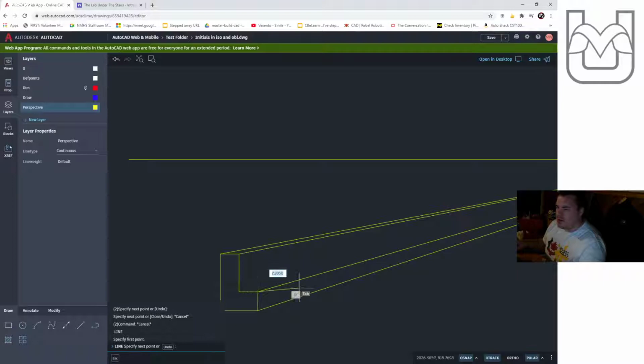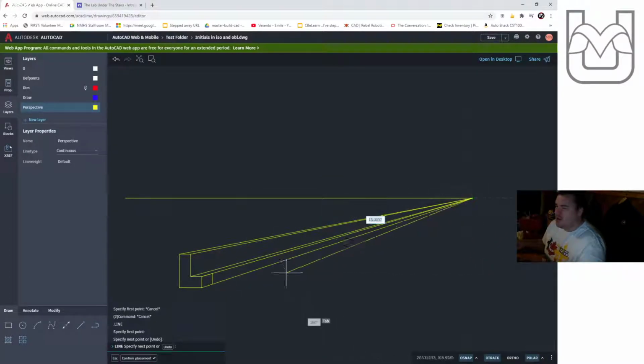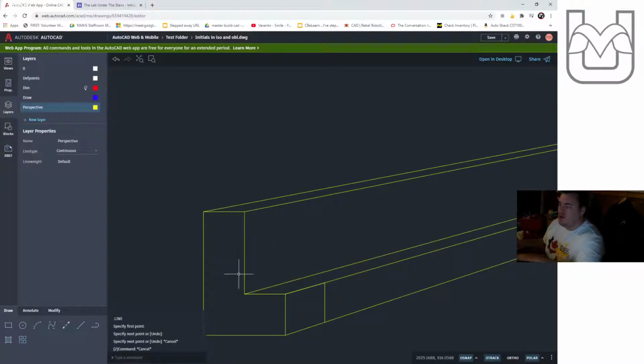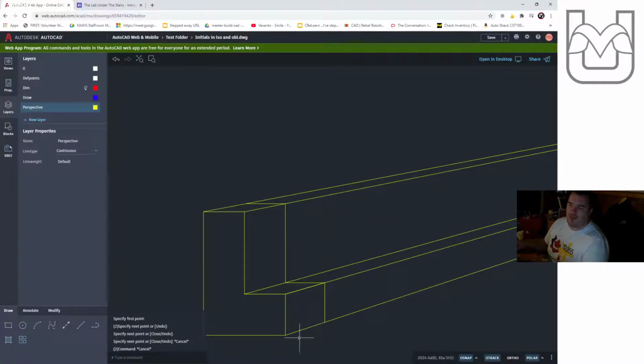And I'm just going to pick the nearest edge to me. In that case, that's this one. And I'm just going to draw it accurately at 1 unit. Okay. From there, I am going to simply follow that 1 unit along. And by simply keeping my horizontal and vertical, so my sideways and my up and down lines consistent, it's going to allow me to actually finish off the rest of this drawing.